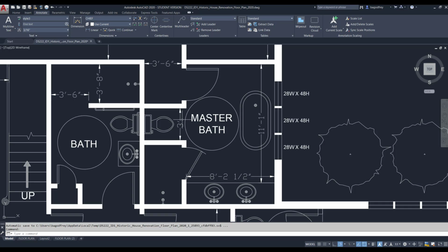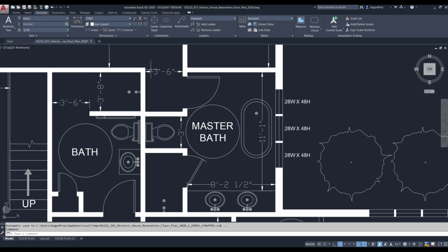Or the 30 by 48 clear space, kind of T-shaped clear space, if you're using that one instead. You're going to give us the general lengths and widths of the space, and then, making sure to show corridors, if there's toilet enclosures, that type of information. So you can be thoughtful about how you put these dimensions in, so it's giving us a lot of information, but we don't clutter it up with just so many dimensions we can't read it.